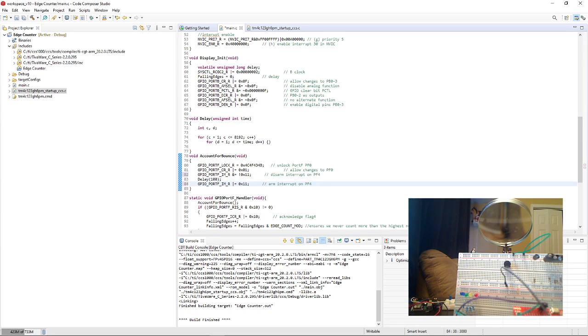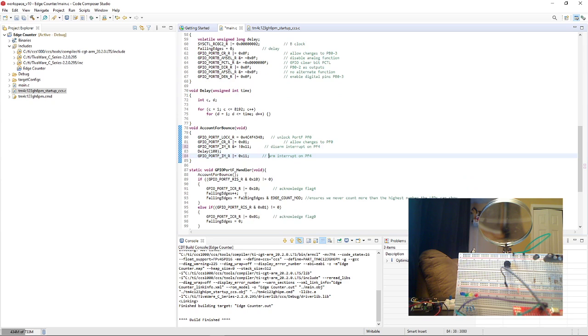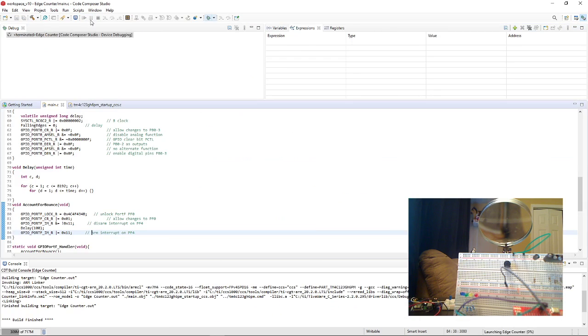So basically, we get an interrupt from here. We don't accept any new interrupts. Then we process the interrupt that we had. And this does slow everything down, but essentially it ensures that all the interrupts that come through, because this will buffer interrupts to a certain extent, are definitely ones that users pressed, and not because the circuitry bounced a little bit.